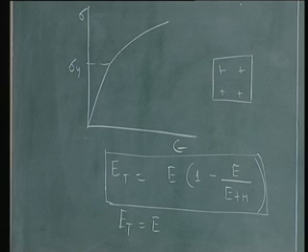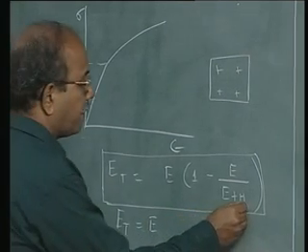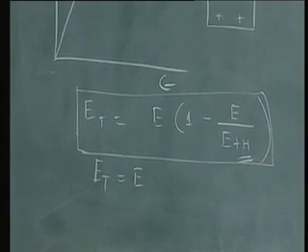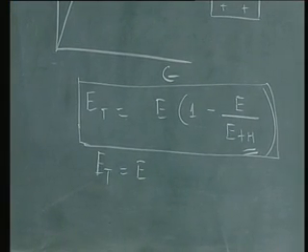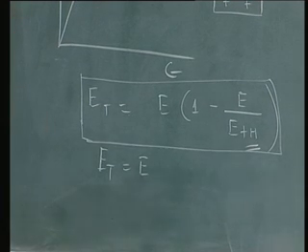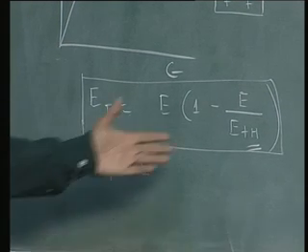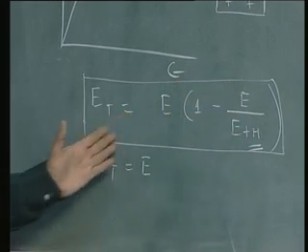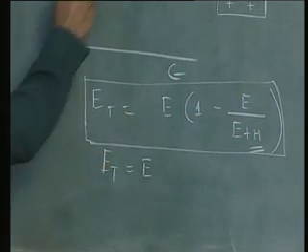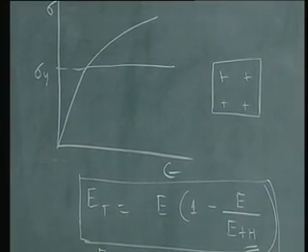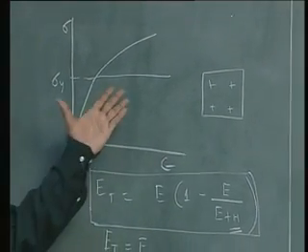Yeah, the next question is what happens when h goes to 0. The stress strain curve, in fact you can see that when h goes to 0, this term becomes 1, so Et becomes 0. In other words, the stress strain curve takes a turn like that, right.